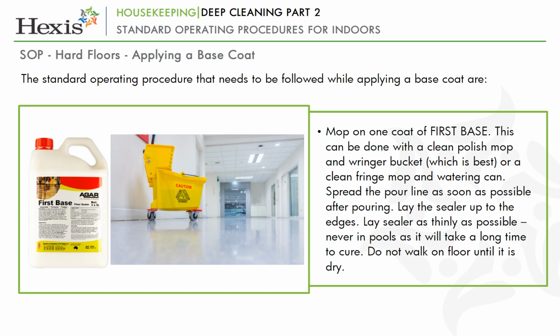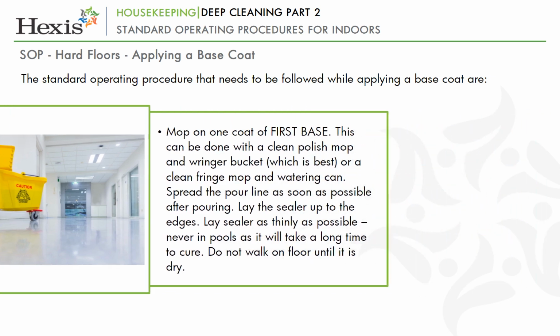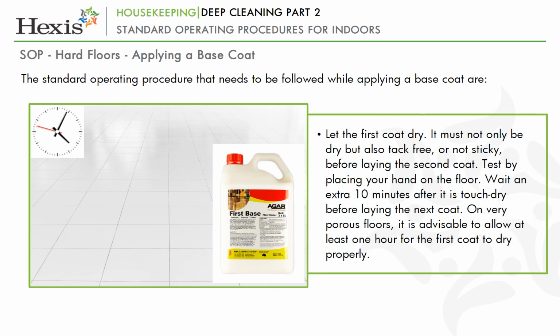Do not walk on floor until it is dry. Let the first coat dry. It must not only be dry but also tack-free or not sticky before laying the second coat. Test by placing your hand on the floor. Wait an extra 10 minutes after it is touch dry before laying the next coat. On very porous floors, it is advisable to allow at least 1 hour for the first coat to dry properly.